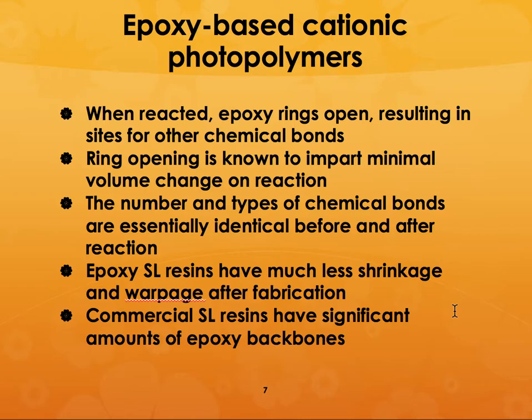Because you do not want residual stresses to be introduced into your part, by doing the epoxy based cationic photopolymers, you can get a stereolithography resin system that does not shrink as much as the acrylate type of resin systems. And the number and types of chemical bonds are essentially identical before and after the reaction.